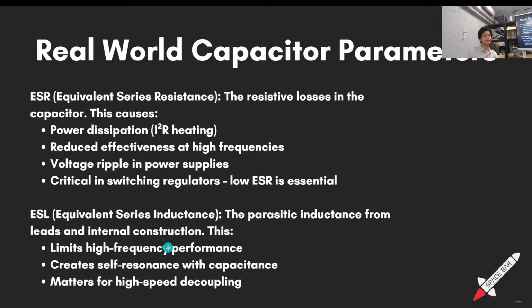Okay. So the capacitor has a resistance and an inductance, and I will explain what inductance is later. But especially the resistance. Dylan mentioned a resistor earlier. Basically, every capacitor has a secret resistor in series with it, because the capacitor has some inherent resistance. This limits how much current can flow through it, and also how much the capacitor will heat up when you run a lot of current through it.